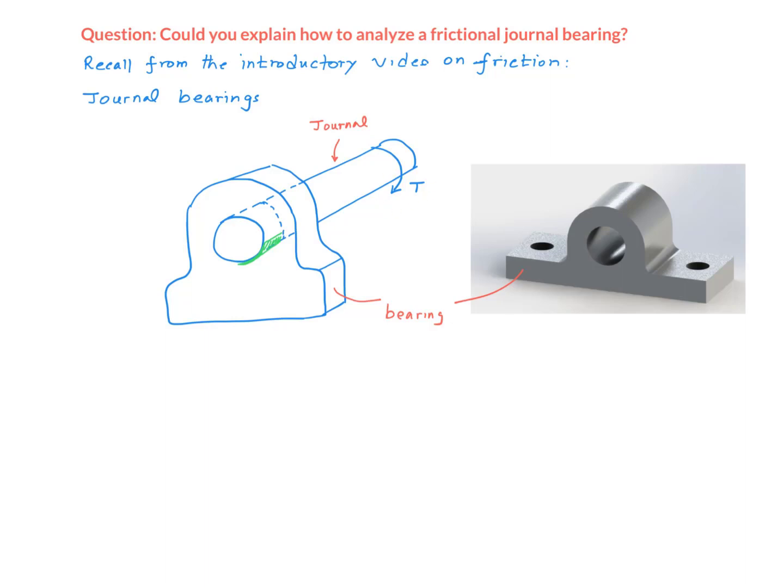So this is the torque that is needed to overcome the resisting torque emerging from the frictional force. If the shaft is spinning at a constant angular velocity and if nothing else is acting, this torque must balance the torque coming from the frictional force in order to keep the shaft spinning at that constant velocity, right?